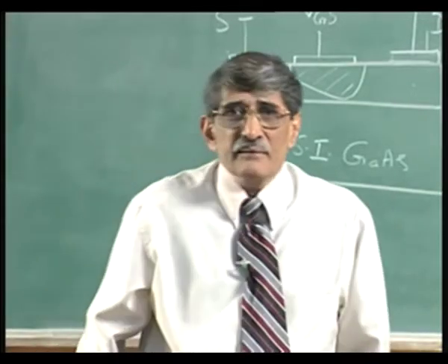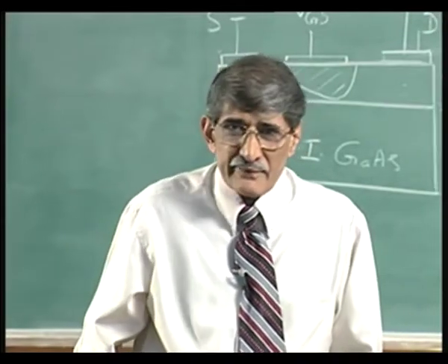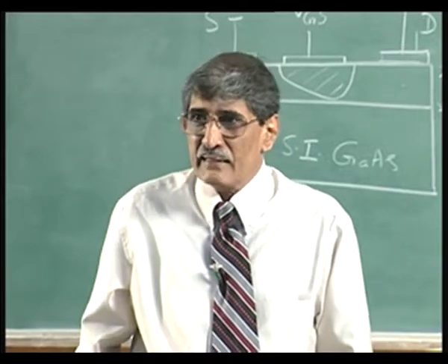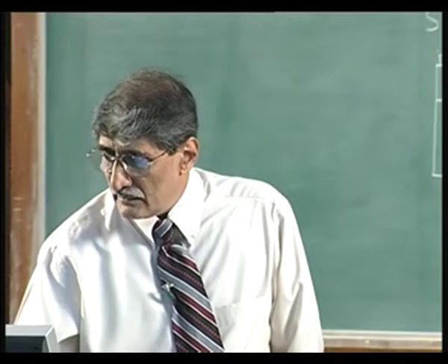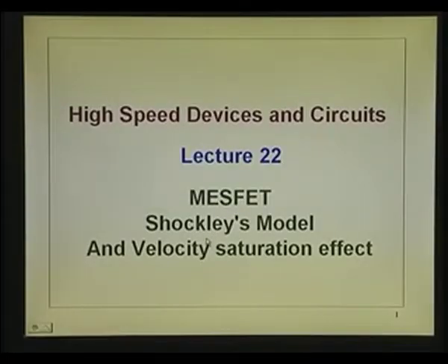So, we have been discussing the MESFET IV characteristics based on a model called Shockley's model. This was the original model given at least 5 decades back, 1950s, but still holds good for most of the structures, unless you have too much reduction in the size.